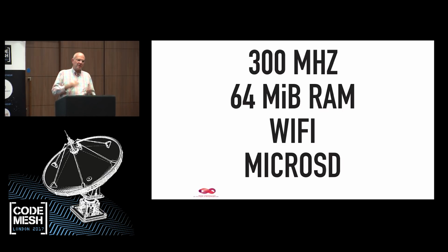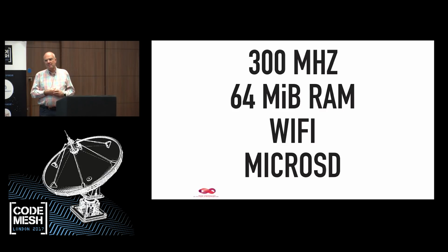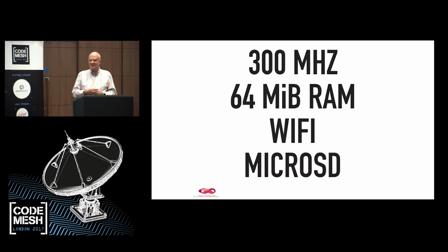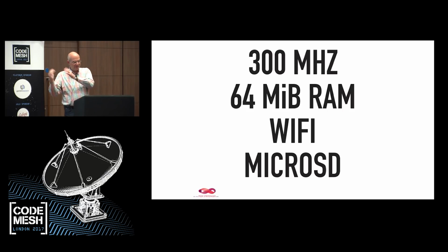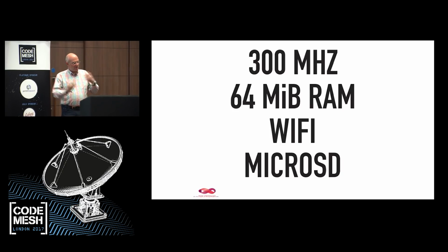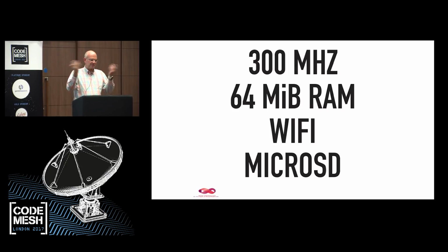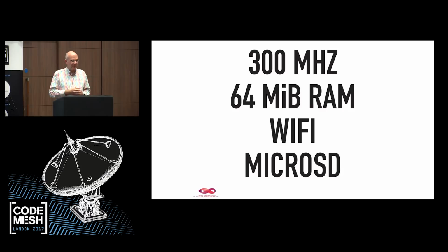We have a version of the hardware basically for industrial use where we don't use micro SD cards because they fall out and they have all kinds of issues. There we actually have NAND flash on the board using the same software stack. But then you need a flash file system, and for the flash file system you need a license, and they are dual licensed. If I do a commercial product, that's fine, because then I just pay to get rid of the GPL 3, 4, 5, whatever they have. But we didn't want to burden the users with this. And if you use SD cards, you get the flash file system or the flash mapping thing for free, and you can just run a FAT file system on top of it for easy access.